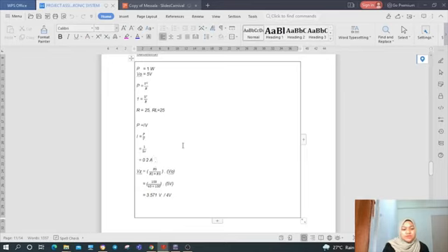Lastly, we calculate the value for Vz. Vz equals R3 divided by R2 plus R3 times V naught. We assume R2 is 40 ohm and R3 is 100. V naught is given as 5 volt, and the answer for the value of Vz is 3.571 volt.